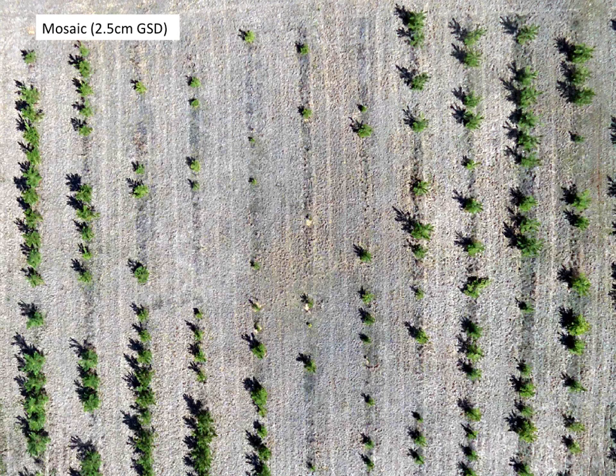So I flew probably about 100 feet, and the ground resolution of this is about 2.5 centimeters per pixel, so we have very good resolution. And because of the study, some of these trees were shin high, and then maybe some of them are waist high to get an idea of the size. But you can clearly see each individual